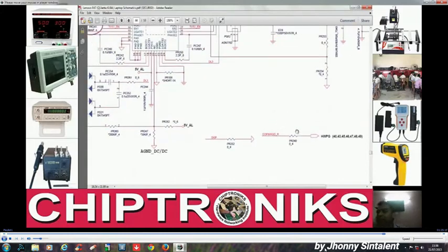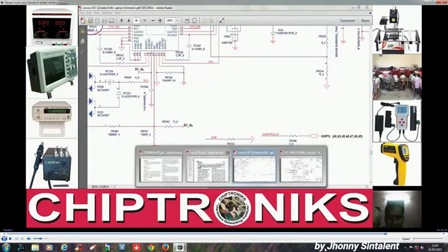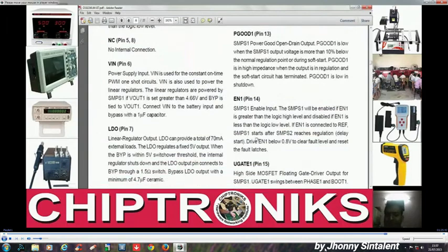And as we have spoken in the third class, all regulators supply power good which will eventually go to the PCH, and which will eventually go to the IO controller, except VRM, which generates power good directly to the PCH.